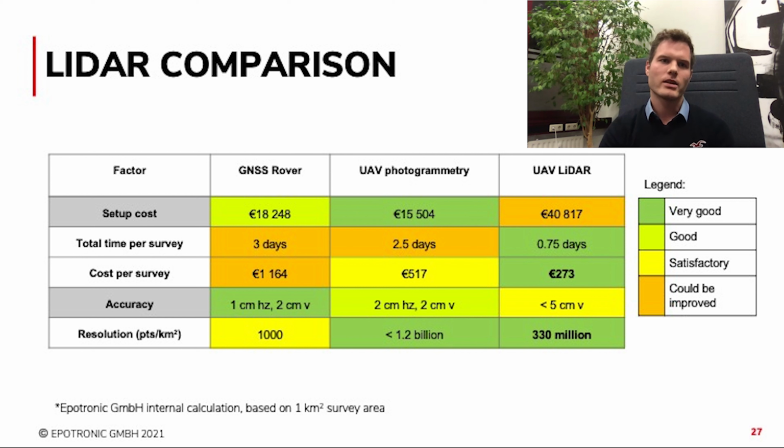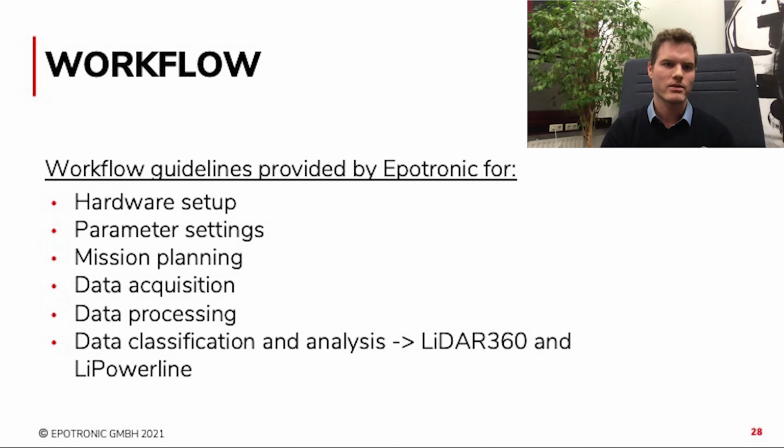In addition to that, you will need to know the workflow setup of this whole equipment. A lot of technology is coming together. So the hardware setup: we have the drone, we have the sensor, we even have the base stations that we're going to utilize, maybe some subscriptions of custom network RTKs. Then we have the parameter settings that we need to think about for the LiDAR itself, depending on which LiDAR would be used. Then we're going to do the mission planning. I think also GreenValley will provide a very nice app for their hardware setups in the future. And then we have the data acquisition, the data processing.